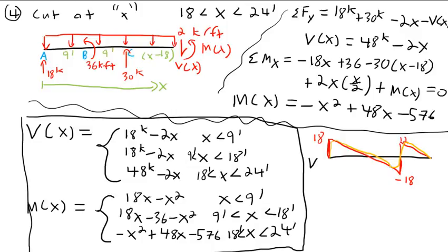Because in reality, physically, this 30 kip point load, what would that be? That would probably be like a big steel column or a concrete pile or something like that. This 30 kip point load is probably transferred through an area that's half a foot across, 6 inches, a foot across, depending on whether it's steel or concrete. It takes a good dimension just to transmit that thing. But we're modeling this as a knife's edge, zero-dimension force. But whatever, for beam design, that's fine. That's why we can have discontinuities in equations, because we're taking physical systems and modeling them with certain idealized models.